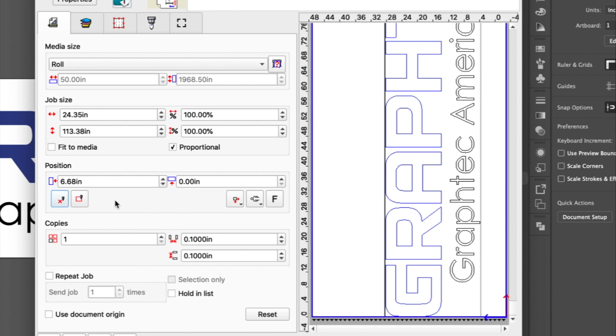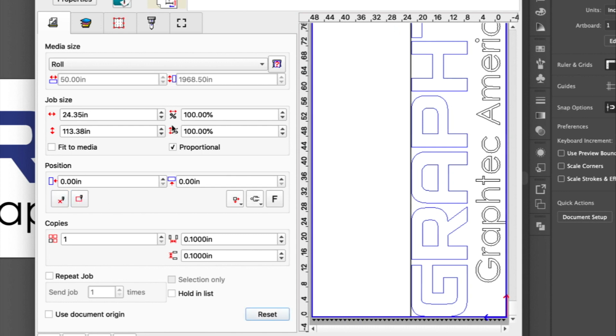The button next to the Interactive button is basically a Show Me button, where, when clicked, it will move the tool head in a rectangular pattern showing the actual size the design will be on the cutter. For a moment, let's reduce the size of the design to a more manageable size.